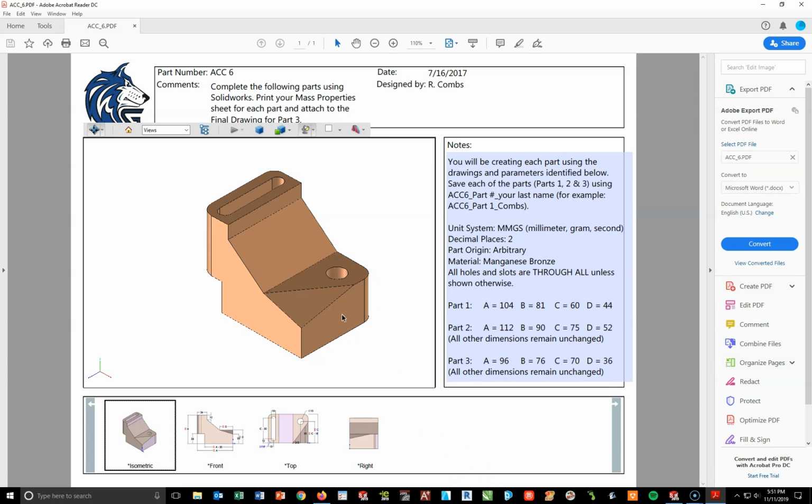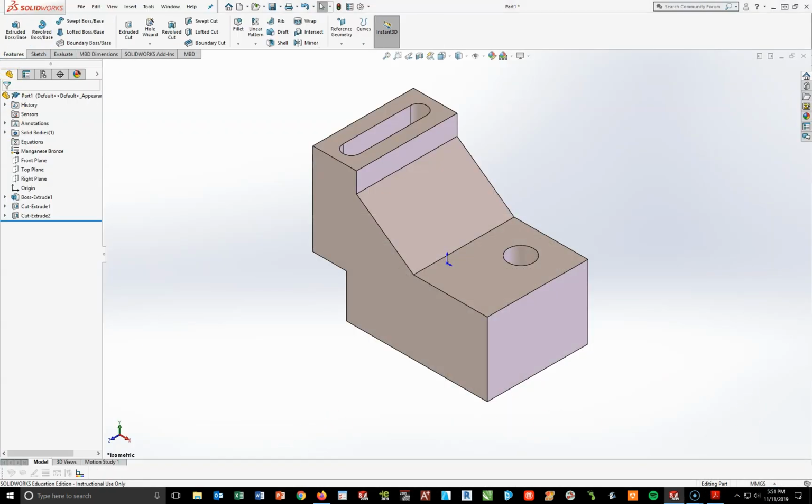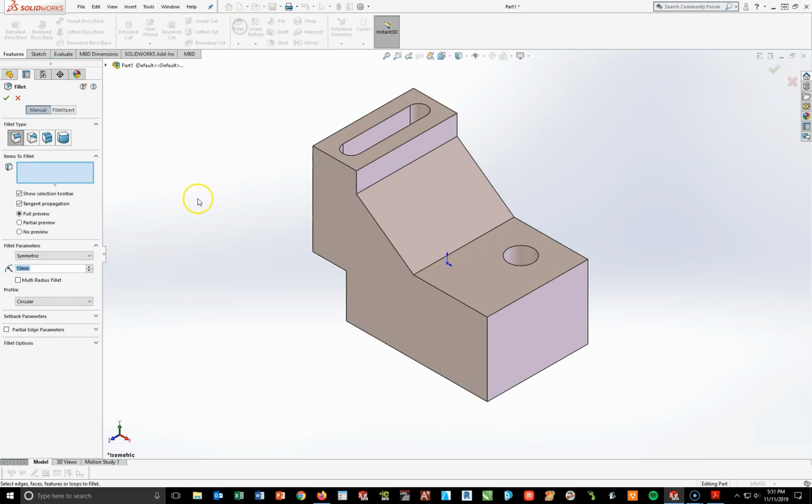And I'm going to use a tool in this case called a feature fillet. So going back into SOLIDWORKS, go to your feature toolbar, and if you look about a little beyond halfway, there's a tool called fillet. So it creates rounded internal or external face along one or more edges, okay, on a solid surface. So I'm going to turn that on.